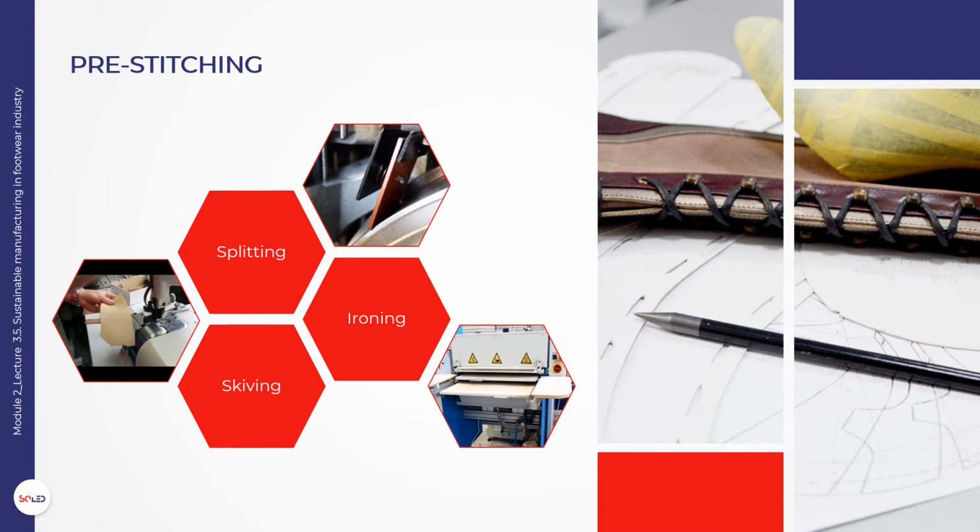Automated skiving machines increase productivity and can group several different operations, saving 3 or 4 manipulations. As far as ironing is concerned, it is essential to control the pressure, activation time and temperature used. Moving away from the recommended parameters will cause rework or reject.